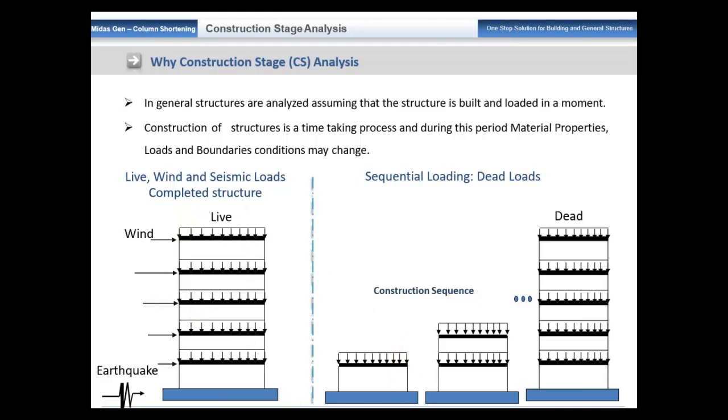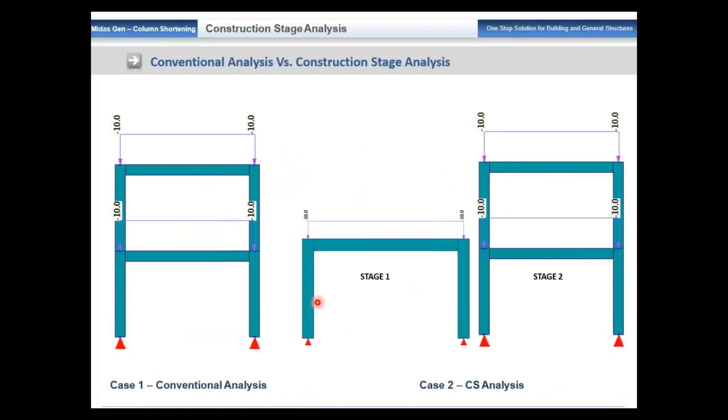We'll just have a look one by one. Talking about the conventional analysis and the construction stage analysis, what difference does it make? As we know today, in high-rise buildings the axial deformations of the columns we cannot ignore anymore, and we require special consideration for both design as well as construction. A vertical member in high-rise structures undergoes both elastic deformation and deformation caused by creep and shrinkage.